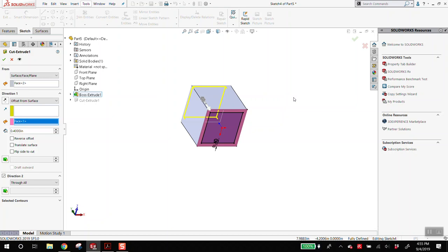Oh, this setting is too big. That's why. Oh, sorry. Okay, yeah, good question. I apologize, everybody. I said the number doesn't matter. However, if the number is really big, like if it's 5 inches, then the cut is a 0 cut. It's like you're telling it to not cut at any depth. So just set this number to something like 0.4.